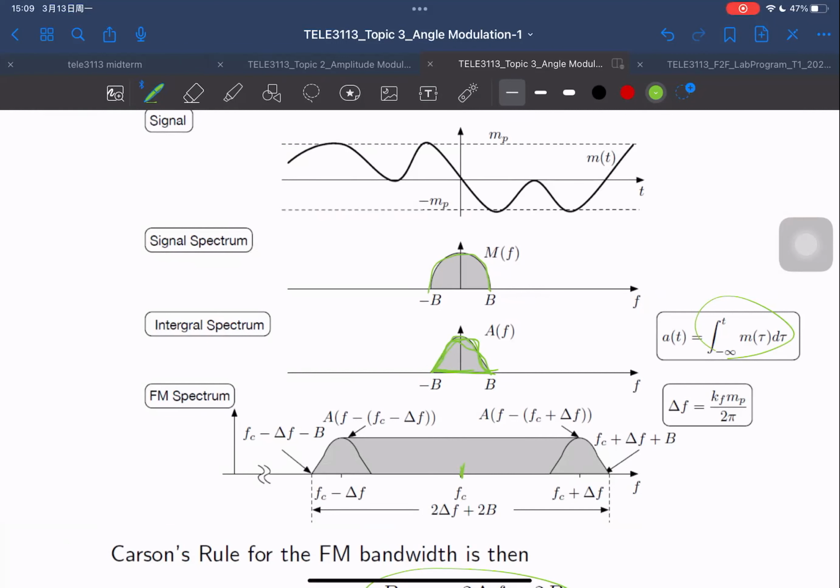For the negative side too. You have to label the amplitude. If you look at the Fourier transform, we're analyzing in frequency instead of angular frequency, so if it's cos 2 pi f naught t, you use half.